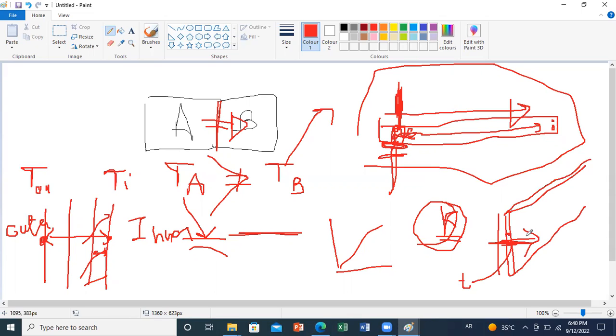The smaller the distance to go over, the lower the resistance to heat. This is why in buildings, since the thickness is small compared to other dimensions, plus the main temperature difference is between the inner and outer sides of the thickness, conduction will mainly be in this direction, and it will be dominant over conduction in other directions.